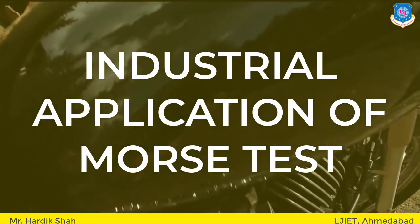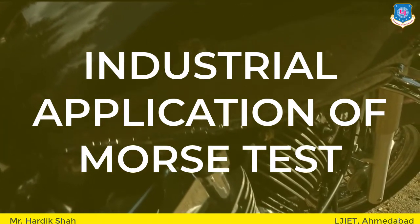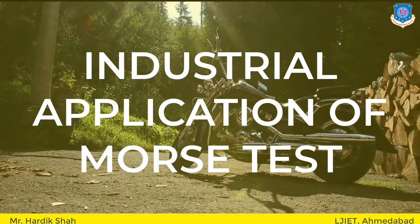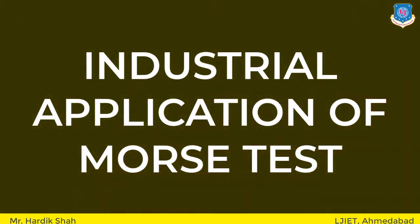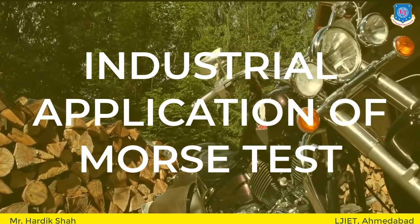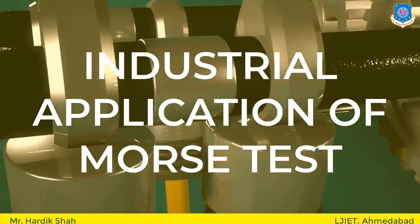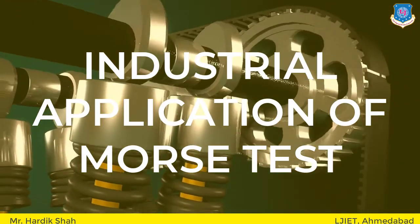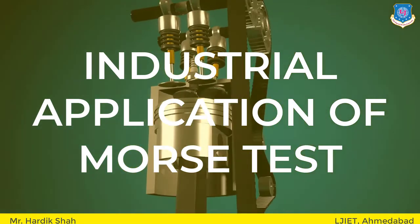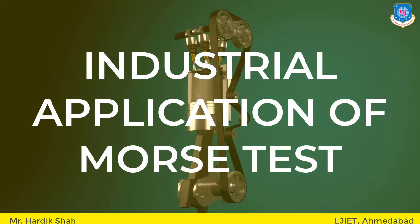Okay. So an IC engine is used to produce mechanical power by combustion of the fuel, and this power is referred to as the rate at which work is done. So power is actually expressed as the product of the force and the linear velocity, or we can say the product of the torque and the angular velocity, right? So in order to measure this power, one needs to measure the torque, or we can say force, and the speed, right? The force or the torque is measured by the dynamometer and the speed is measured by the tachometer. So the power developed by the engine and measured at the output shaft is actually called brake power.